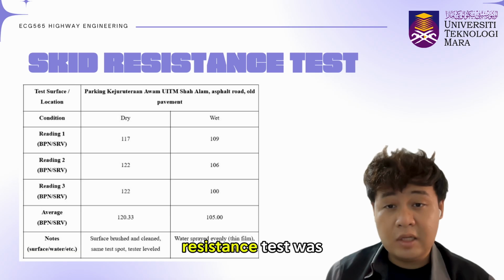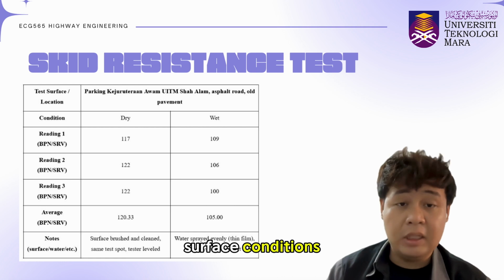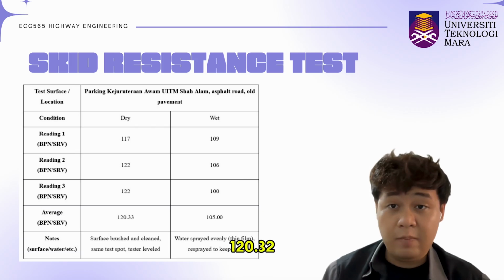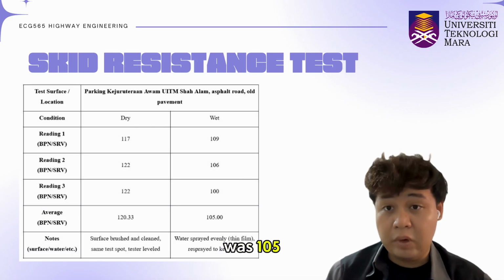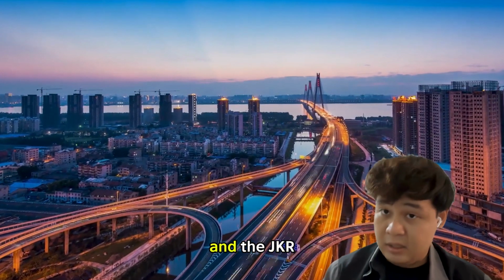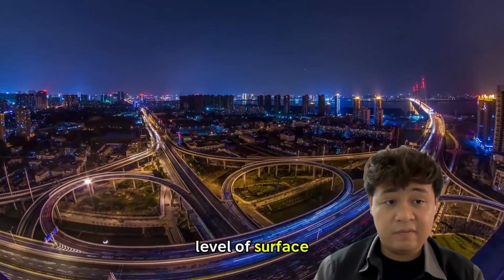The skid resistance test was carried out using the British pendulum tester under both dry and wet surface conditions. The average skid resistance value under the dry condition was 120.33, while under the wet condition it was 105. Based on standard guidelines, a value above 65 indicates a high level of surface friction.